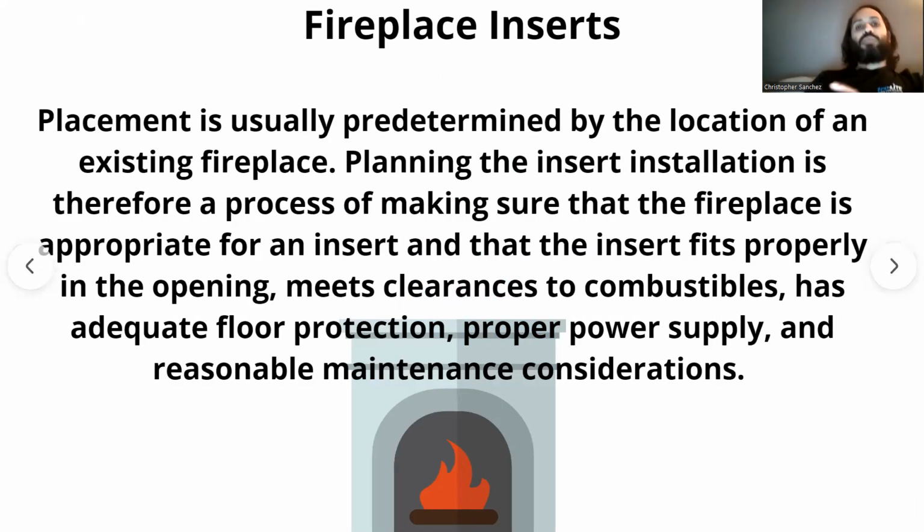Fireplace inserts. Placement is usually predetermined by the location of the existing fireplace. Planning the insert installation is therefore a process of making sure that the fireplace is appropriate for an insert and that the insert fits properly in the opening, meets clearances to combustibles, has adequate floor protection, proper power supply, and reasonable maintenance considerations. So inserts, we get this all the time. The most confusing thing is gas logs versus inserts. Inserts obviously are for existing fireplaces, but they will be piped as well. So it won't just be a log set. You're going to have a whole system going in there.